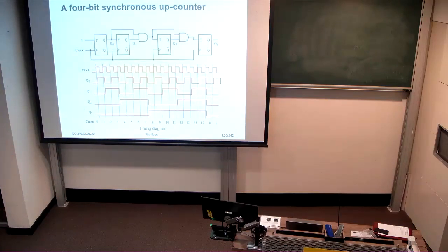So what we should do to build a synchronous counter is to build it in this way, where the one clock signal drives all of the T flip-flops, and it's the Q signals that are telling us when a T signal should be driven here, albeit that the most significant bit is going to have to look at the Qs of all the less significant bits before it knows that the T is asserted here.